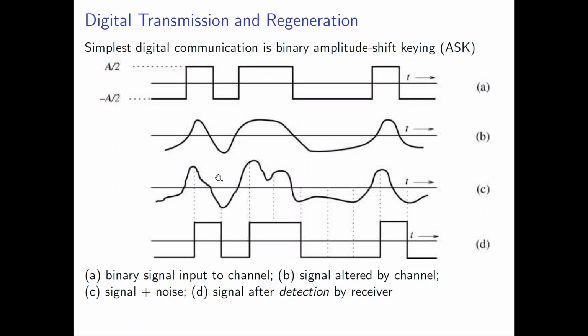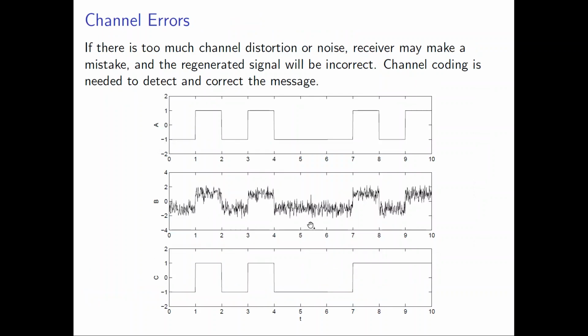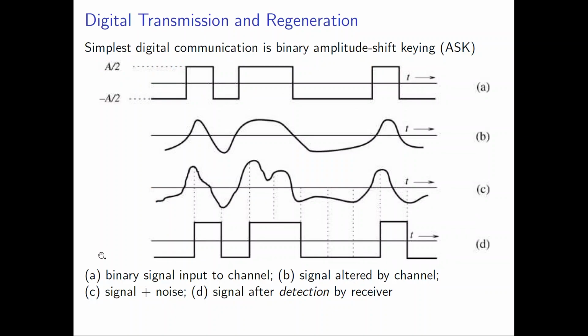This is the mapping you use at the receiver, and then you get this nice shaped signal. And what do you do then? You come here: this is negative, 0; this is positive, 1; negative 0; then positive 1 1; negative 0 0 0; and then positive 1 0. You get your data bits, and then you convert your data bits to the message or text or image or video.